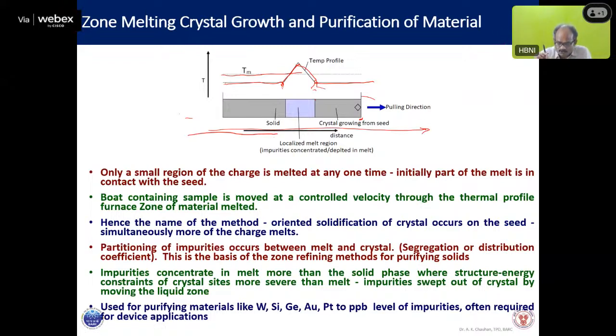Now if you want to make use of the seed, the crucible position should start from this place. Otherwise, if you start from here, your seed will also be melted.